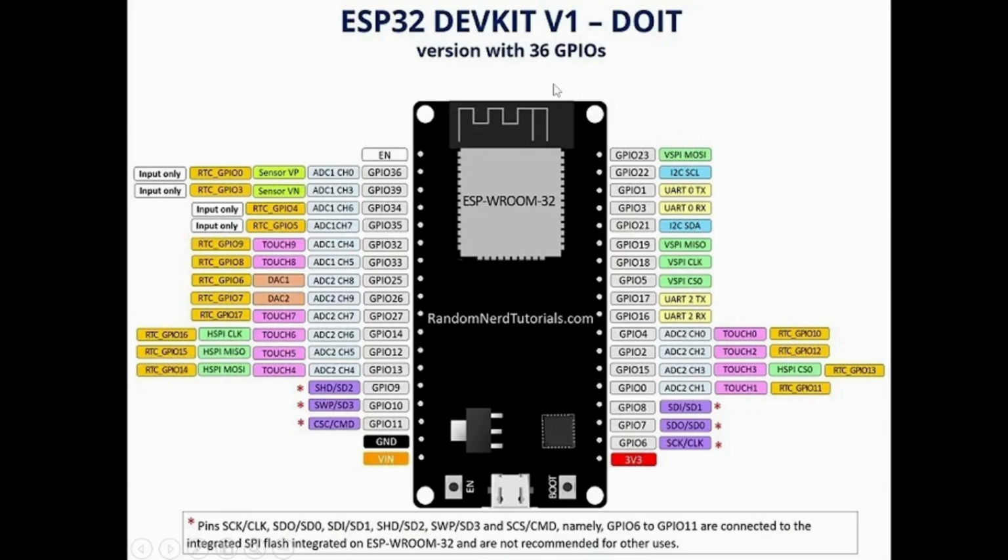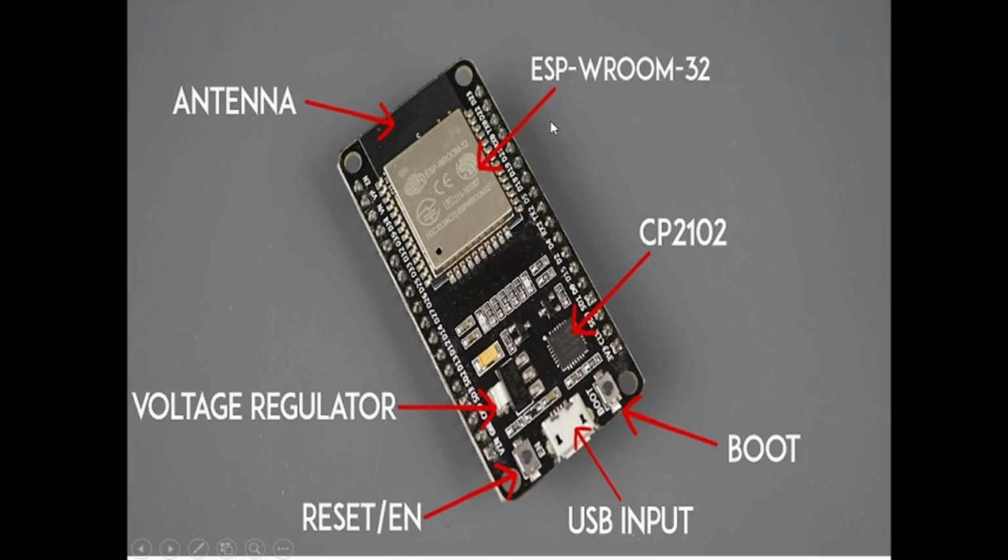Now this is the ESP32 board; actually, ESP32 looks like this. This is a USB input. This USB port is used for two purposes. The first is to upload the program: you connect one end of this cable to the computer and the other end to the ESP32. The second is to provide the initial 5 volt operating voltage, or 5 volt power supply.